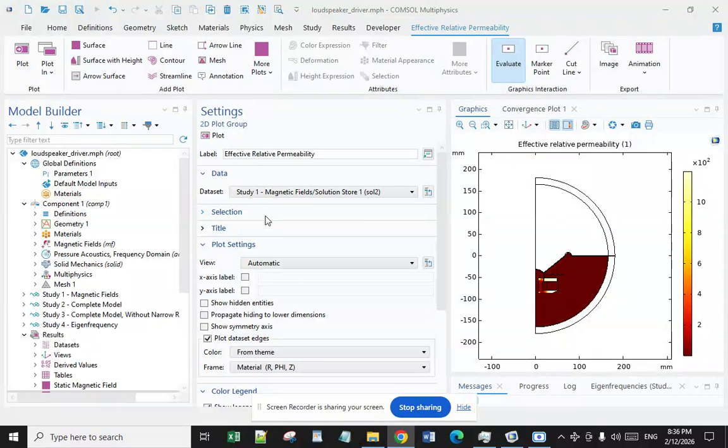The fourth one is less sensitivity to surface conditions. With contact-based piezoelectric transducers, the test surface has to be machined smoothly to ensure coupling. Using electromagnetic acoustic transducers, the requirements for surface smoothness are less stringent. The only requirement is to remove loose scale and slag.